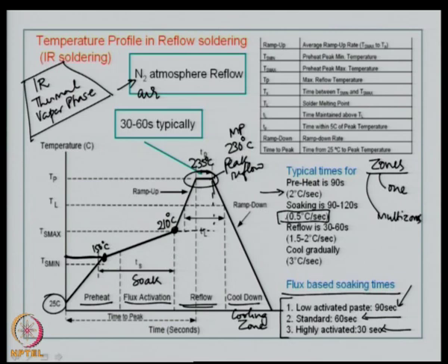The advantage is that there will not be any solder bead formation, there will not be any spattering of the solder paste material, and you will have a very good activated solder paste ready to reflow. At this stage all the solvents are gone, the flux is activated and the tin lead is ready to fuse